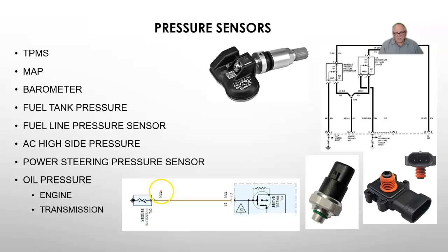I'm going to unplug this wire right here at the sensor. The reason I'm going to do that is because if this gauge isn't working correctly, and the other gauges on the car are, it's either going to be this gauge is faulty, the wiring's faulty, or the sending unit's faulty. The sending unit lives in the harshest environment. It's the most likely to fail. I'm going to unplug this tan wire, key on, this gauge should read all the way down to 0.